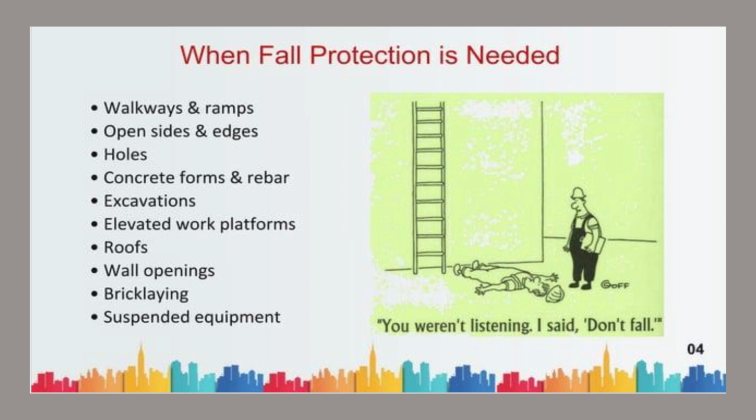When fall protection is needed, now let us see when fall protection should be employed for safe completion of the job. When a worker is on a walkway and ramp, open sides and edges, holes, concrete form and rebar, excavation, elevated work platform, roofs, wall opening, bricklaying and suspended equipments. Workers working in the above situations must use fall protection for safety.